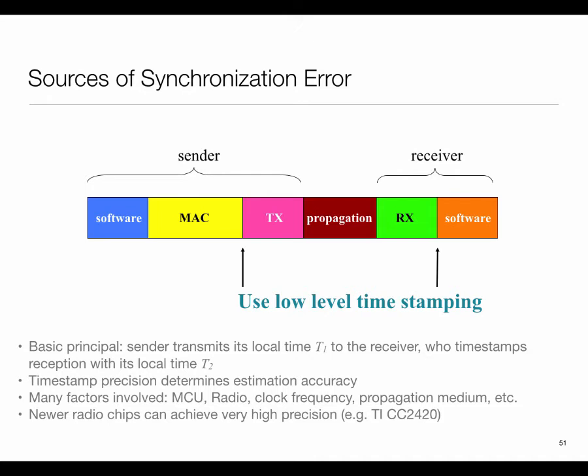What else can confound this picture? So that's one, and you could argue that I can characterize it. The problem is its delay is often very variable, but okay, so that's one source of problem. What's the other source of problem? The second source of problem. The interrupt will not fire at that time because of some other processing of the other interrupt. Right, some other entity may have disabled it, which is almost every operating system. There are times in which it disables the interrupt.